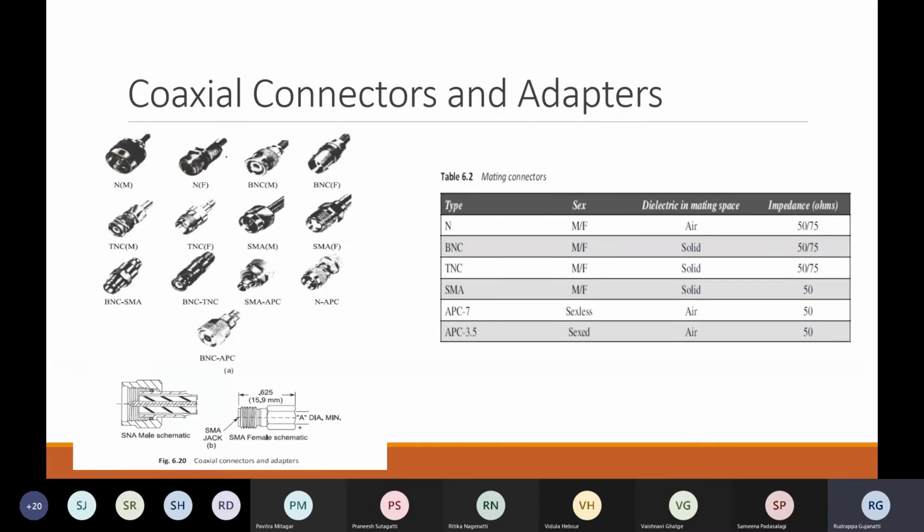So these kinds of devices will be classified as female connectors. In a few, you will not have both, for example APC 7. You will not have the specification regarding the connection, whether the threading is outside or inside. In such cases, sometimes we just have a hook wherein we just rotate. On the CRO, you might have observed those things. You rotate and they both get connected. You don't have threads present over there. So those kinds we classify as neither male nor female.